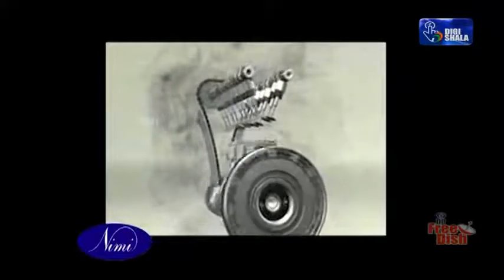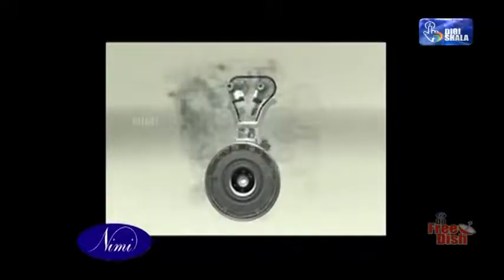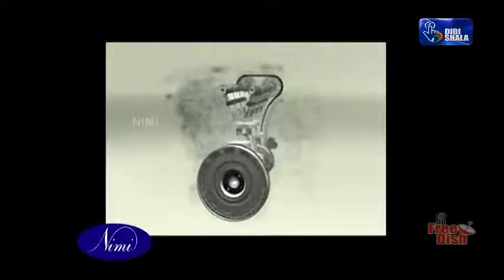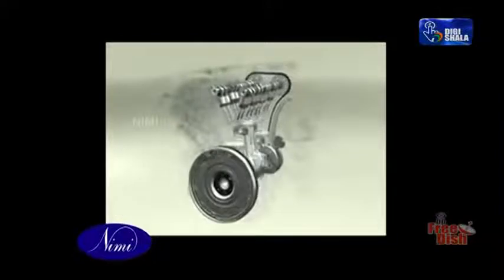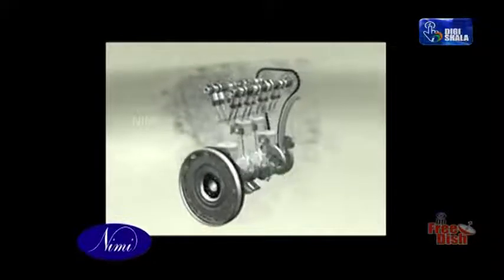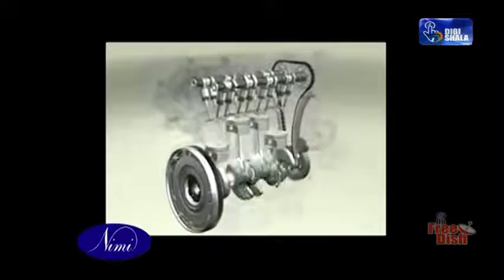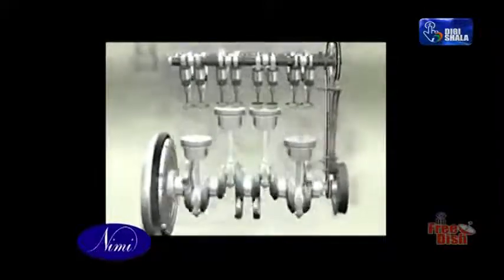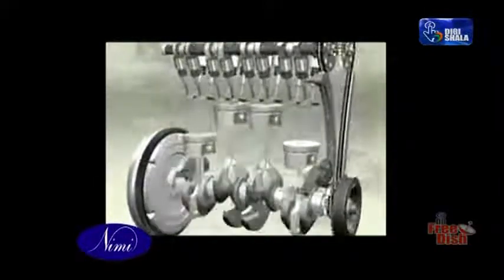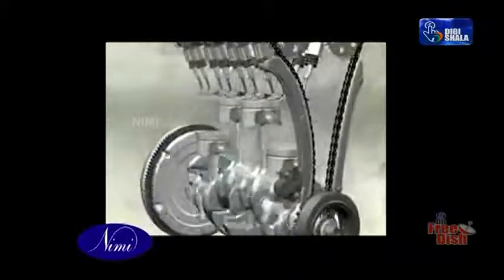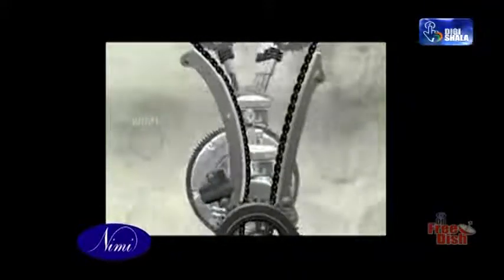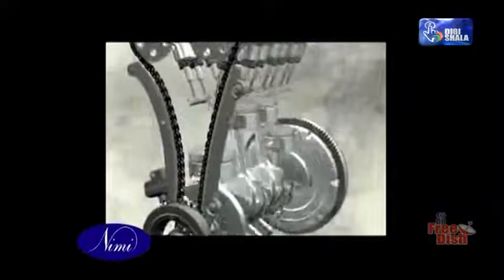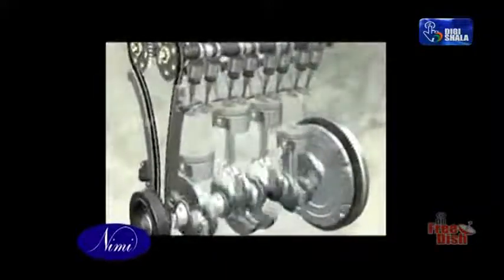A flywheel and its need. A flywheel is needed to drive the crankshaft during the time that the engine is performing the non-power strokes. The flywheel carries the engine over the non-working strokes. Multi-cylinder engines. A smoother flow of power from the crankshaft is obtained when more than one cylinder is used. The extra power impulses are spaced out evenly throughout the 2 revolutions of the 4-stroke cycle. The flywheel of a multi-cylinder engine is lighter in weight.